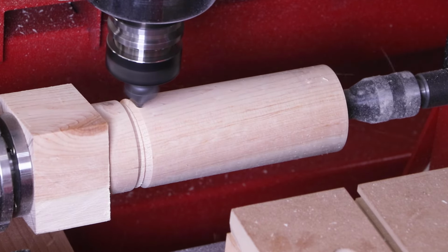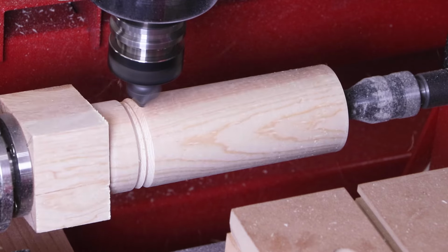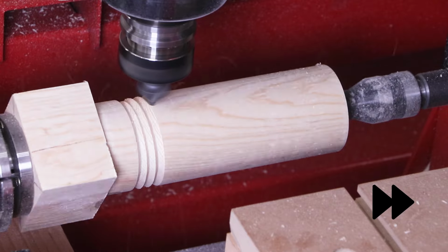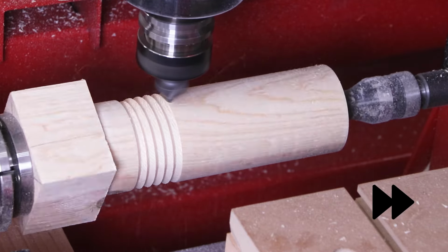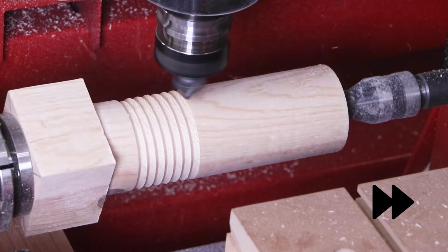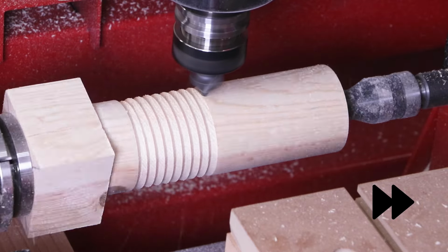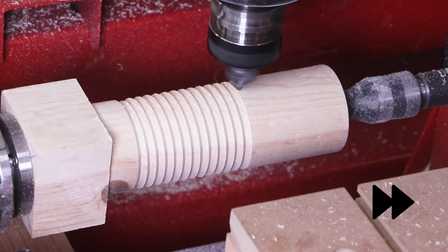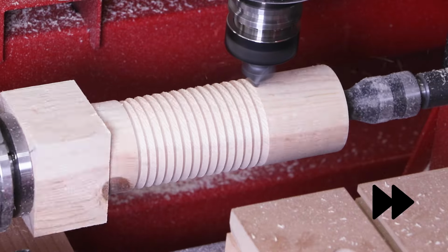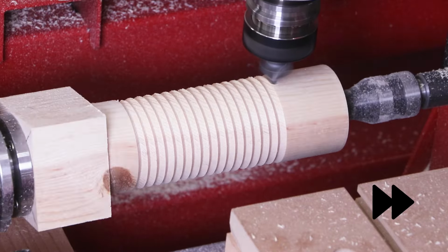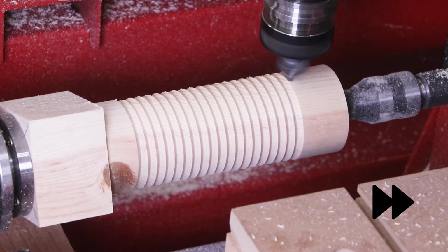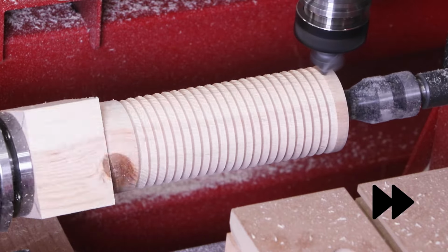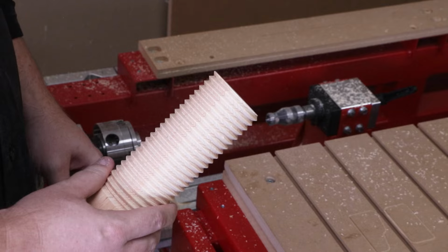The cut depth was automatically calculated, but with a 90-degree V cutter, this is actually cutting 1/8 inch deep into the material. Now, the cutting speed is not very fast for this process. That's because all the cutting taking place is actually cross-grain cuts. And because the threads come to very sharp points around the entire process, we want to minimize that tear out that could take place around these wooden threads. All the cutting advantages shown here are automatically implemented into CCAM Pro. The reason we chose 4 threads per inch is to match the internal threads of this wooden component.